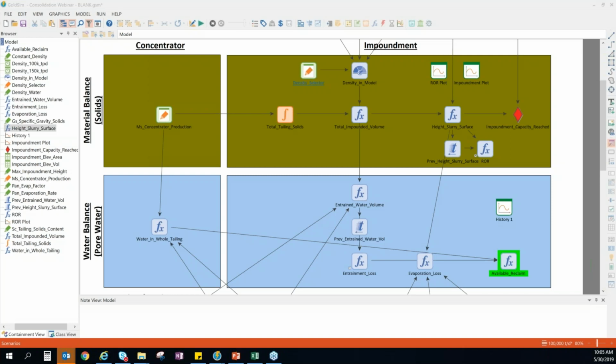Okay, so for a new facility, a lot of times we will have developed a pilot scale crusher plant or a crusher facility. Okay, and the tailing that comes out of that, we can get some representative samples. That's about as close as we can get to a true sample of what's going to be coming in the future. And we can use that to estimate things like beach slope, material properties for consolidation, but really it's that beach slope.